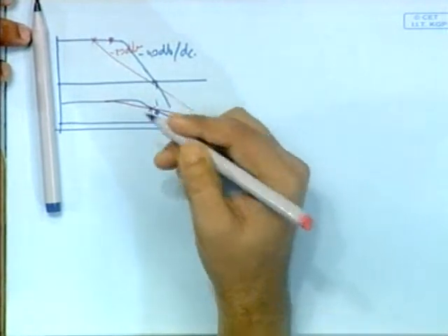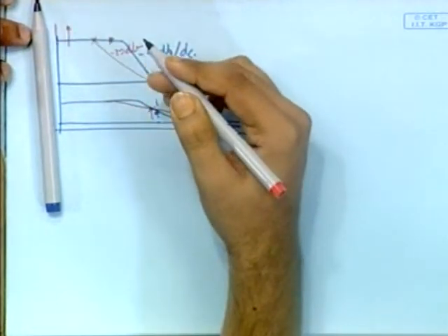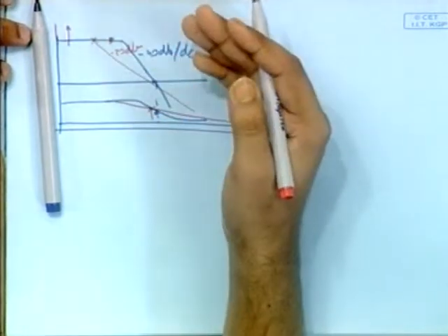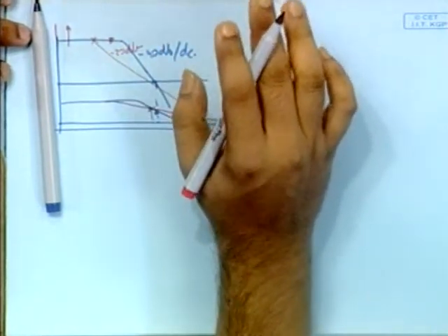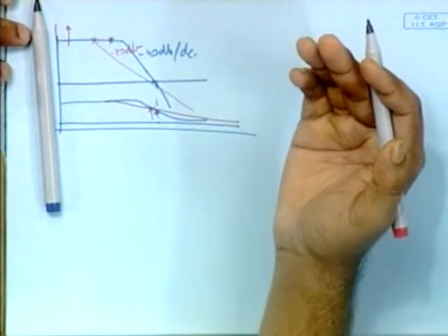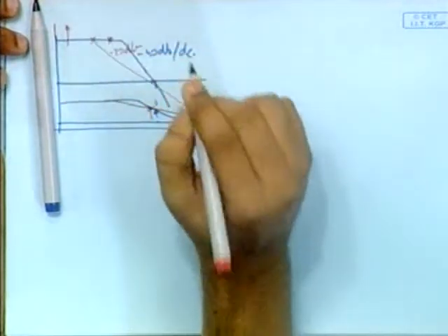Similarly, another action that you may take is to increase or decrease this gain, as may be the case. That will vary your phase margin. These are several handles that you have on your phase margin. How to actually do this, I will show you later, because you don't yet have the expertise of calculating the poles, zeros and placements. So you may increase this gain, that's one handle.